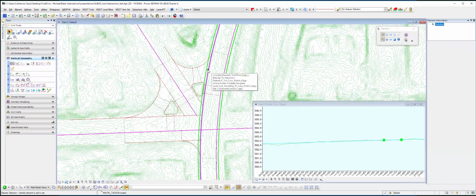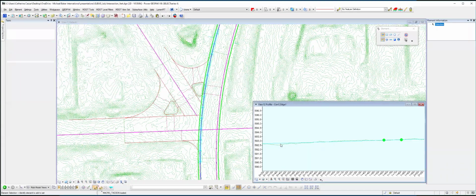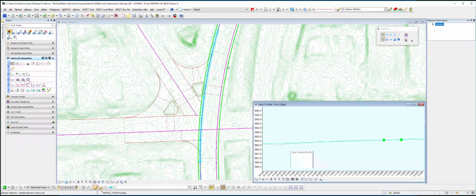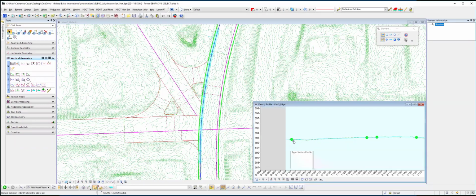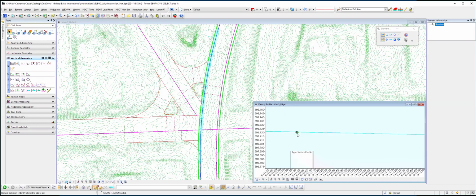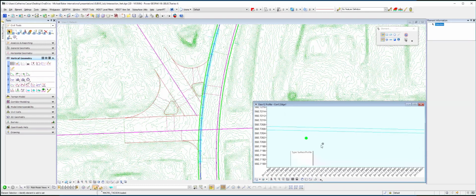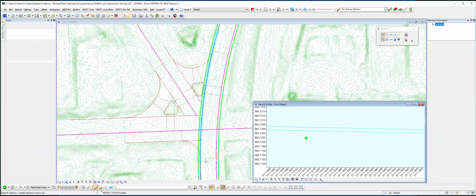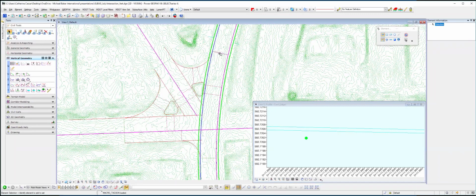So from this modeled edge, I also took a profile. Now, this roadway is in a vertical curve, which causes a number of issues that you should be aware of. These are some pitfalls you can run into. So you notice the difference here. This intersection point is this point right down here. This one up here, sorry. Mainline limit 1. Limit 1, yes. Or it's the south limit. So it is this one.